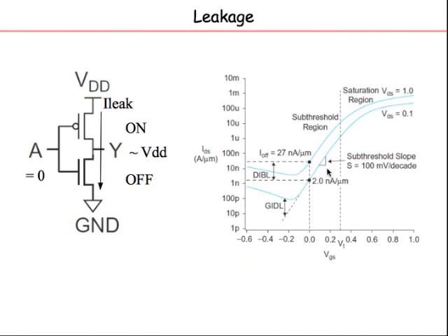The other important thing is here. When VGS is 0, in the ideal model, no matter what VDS I apply, the current should be 0. But here there is some current, 1 nanoamp, 2 nanoamps. Similarly, if I increase VDS, the current goes up. So that means you have some current. These currents are called sub-threshold leakage current because I am less than the threshold voltage. There are certain additional features here. We'll look at them later, maybe in the next lecture: gate-induced drain leakage, drain-induced barrier lowering, etc.